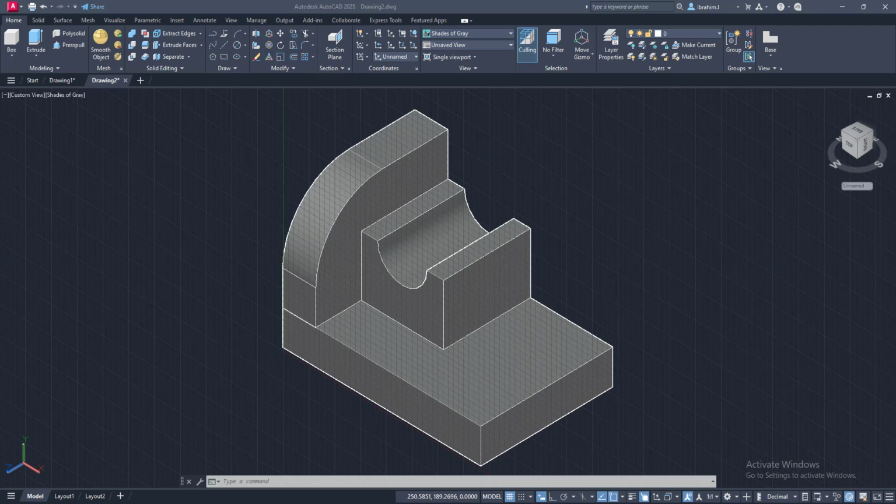Instead of wasting our time, there's a way we can proceed with this one. I'll go ahead to select my line command very easily. When I start my line command and come to this edge here, thank God for object snap tracking. I'll just move my mouse along that same line of the object snap, and I'll enter the distance of 12, to start my line at a distance of 12 away, right? Note that you have to have your object snap tracking on so that it keeps this line on a straight line. Remember the auto mode, right?